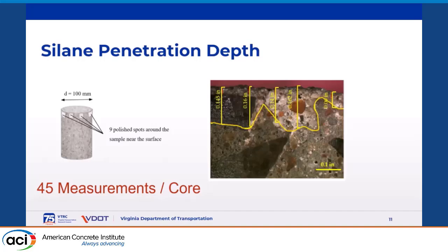The silane penetration depends on many factors. For example, the surface tension of the silane itself, the viscosity of the sealer, or the concrete properties and porosity; everything can impact the silane penetration.